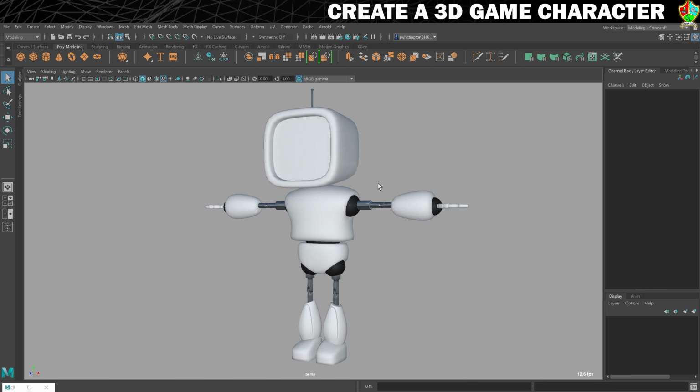In the next one, we're going to work on the face, and for that we're going to need to bring in a texture, do some simple UV mapping, create the material, and then apply it to those faces. So let's move on to that.